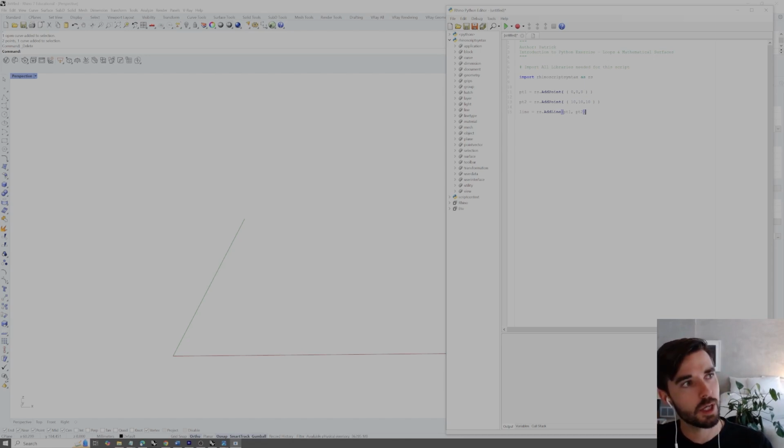Like in previous videos, we want to go from a line now to multiple lines which construct a polyline. In order to do this, we need a list of points. So we could just go ahead and keep adding our points. So we could make a point3, and we could say 12, 12, 16 to just change it up slightly. And instead of adding a line, we can comment this line out, and now we can make a polyline variable called polyline, and we can set this equal to a polyline function called add polyline. And what this takes is a list of points.